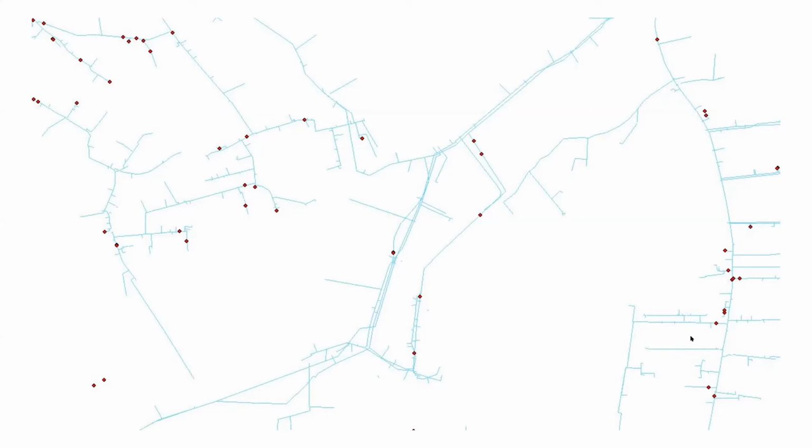But you'll also notice that there are still breaks floating out where there is no mapped pipe. And we were able to run another query to figure out the straight line distance from those types of breaks to the nearest pipe to get a rough idea of how much was missing. It's not going to be a perfect number, but they know more now than they did before. And this is information, again, that would not have been easily collectible without using a GIS system and GIS analysis.